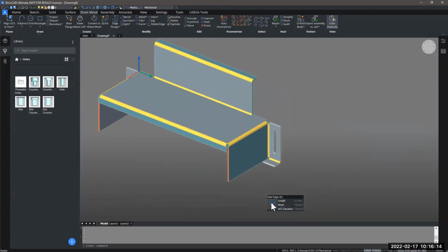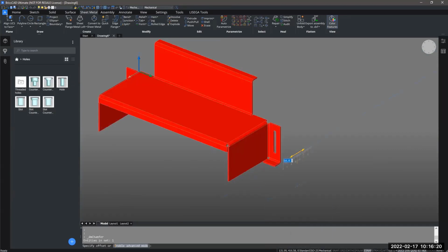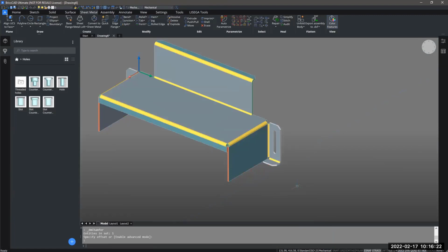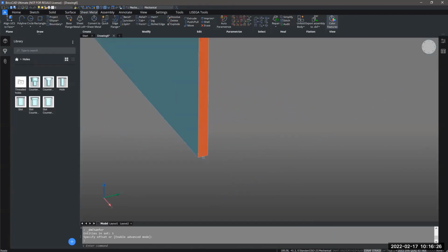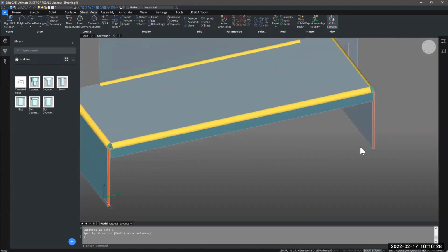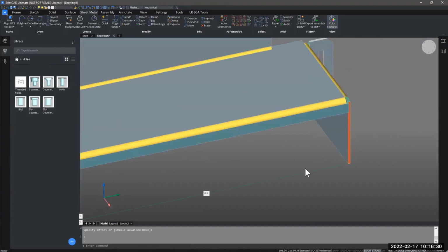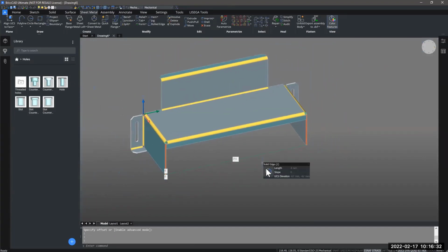And in the quad, I can select the chamfer tool like so and give it a value of 5 millimeters. Just to round out that design a bit more. I can also add a chamfer on these parts, but I can make it a bit larger and make it 50 millimeters.